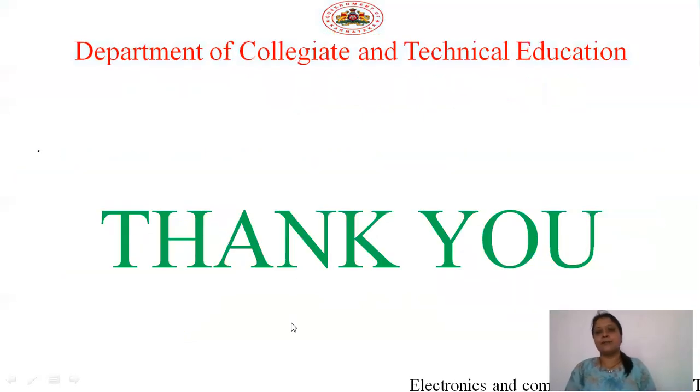Now, this completes the session on radar displays. That is, radar displays means the displays which we use in radar applications. Mainly two types of displays: one is the A-scope display, another is the PPI display. A-scope display makes use of the deflection modulation technology, and PPI display makes use of the intensity modulation technology. In case of the A-scope display, two planes are used, horizontal and vertical.